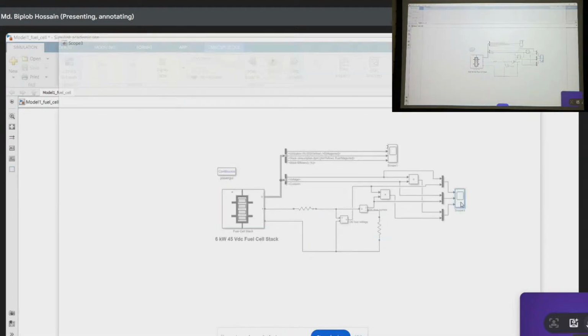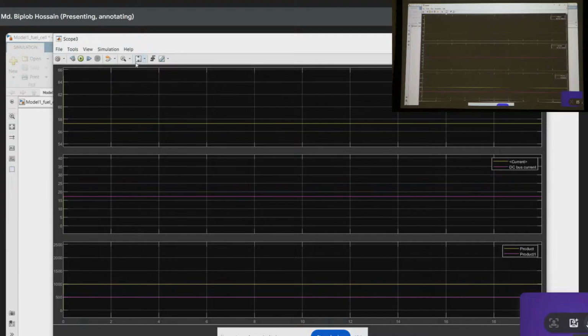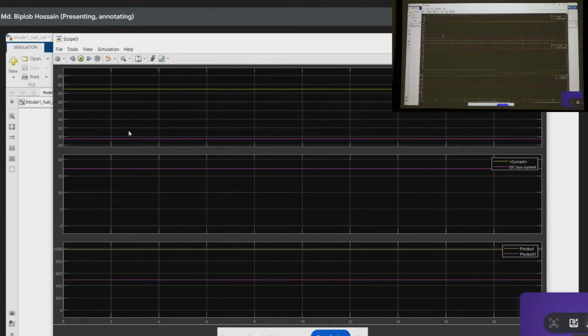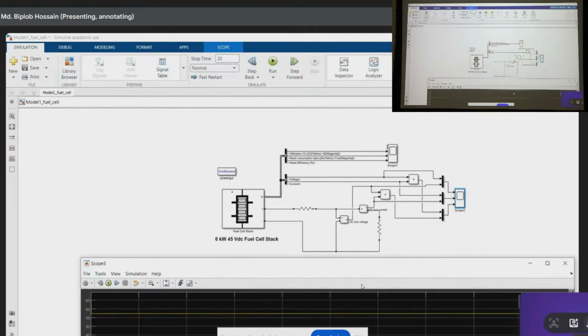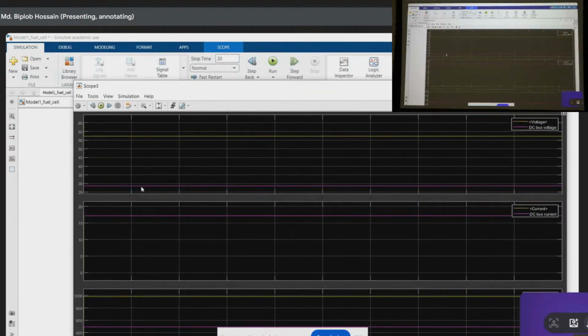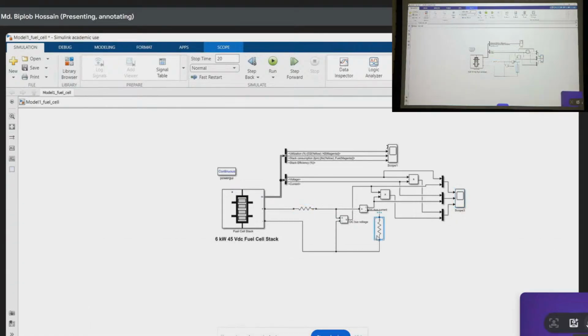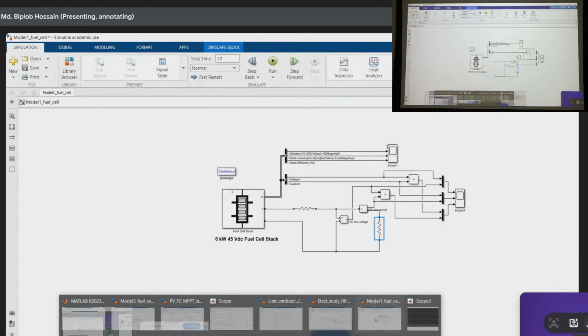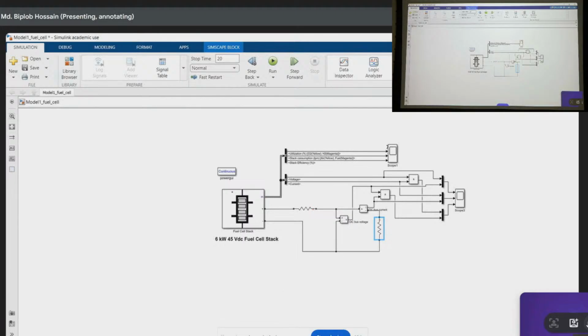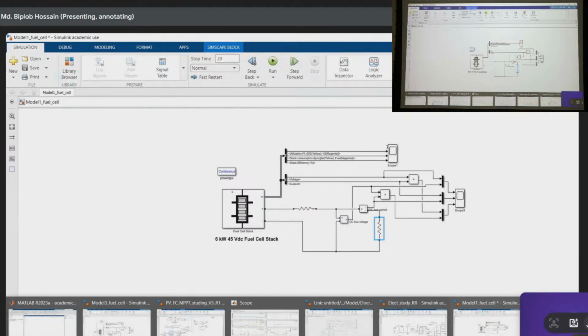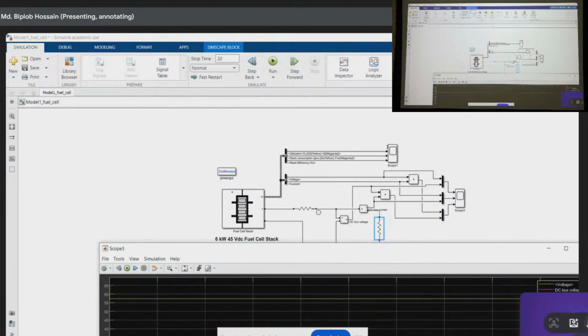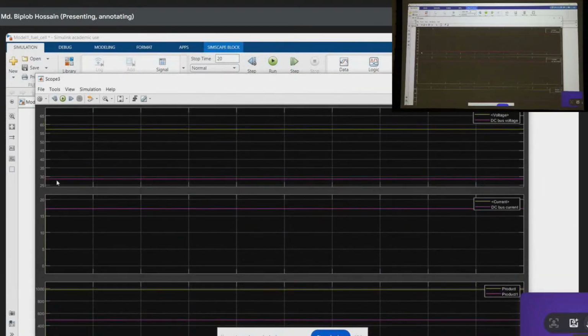For example, you see now the voltage across this one only is reduced, since the branch resistances of this one and this one are equal, that is why the voltage is reduced to half, 45 to half, I think. Here we see this is almost half of this. So this way we can see the results.